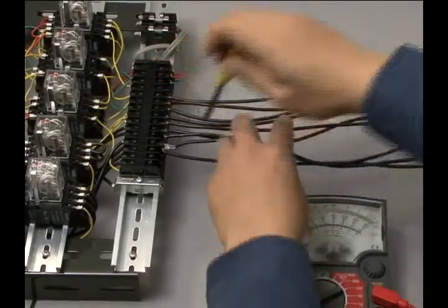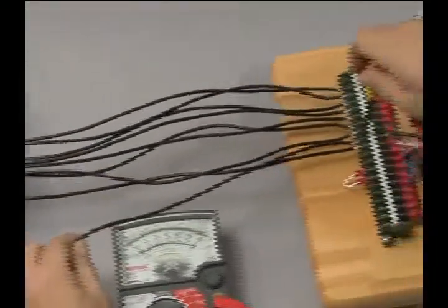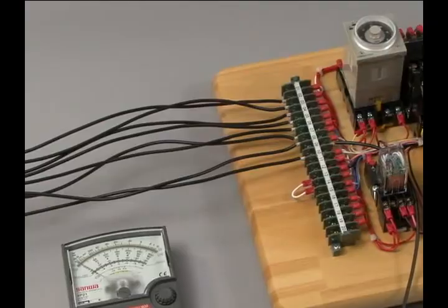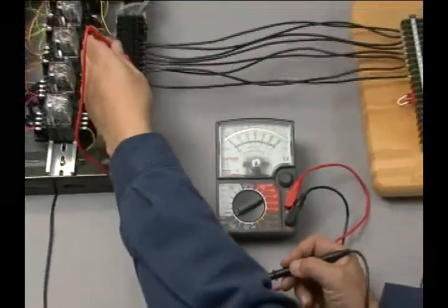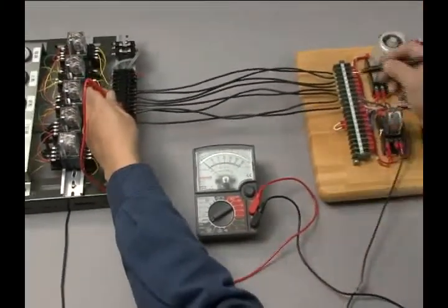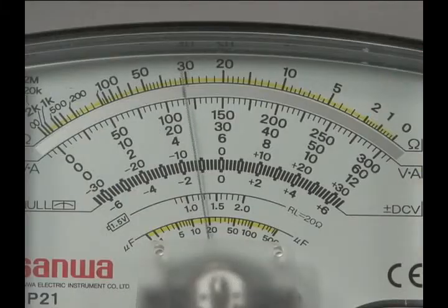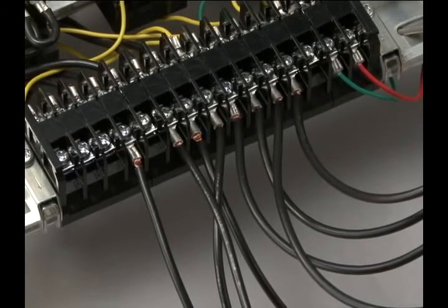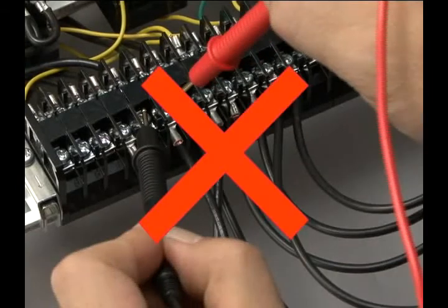Remove terminals from the circuit and the electrical equipment whose current is to be measured, and touch the test leads in such a way that the tester is serially connected to the terminal. Approach this activity with care, because it only takes a fraction of a second to damage the tester if the test leads are allowed to touch parallel to the circuit.